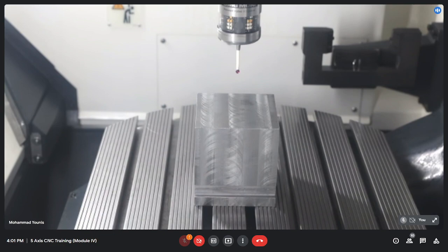So this was about work offsetting, how we set the work offset and how we tell the machine that this is the origin point. In a similar way, we can set any number of work offsets on the workpiece, and we have many cycles for different types and shapes of workpieces. So this was all about work offsetting. Now we'll do some machining. For that, I'll first clamp this workpiece onto the table, and then we'll operate some machine cycle.